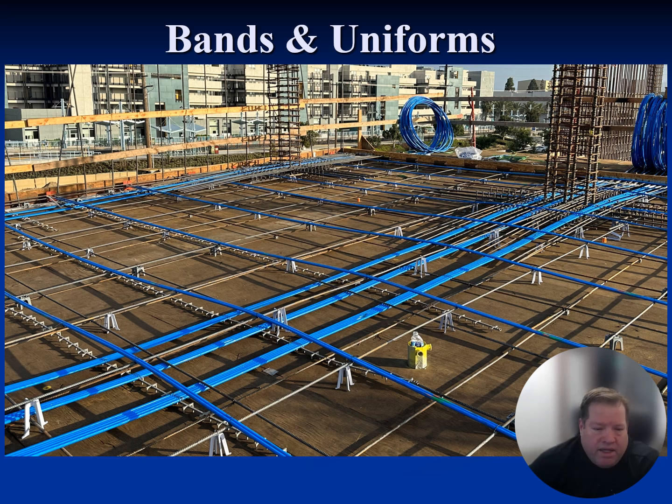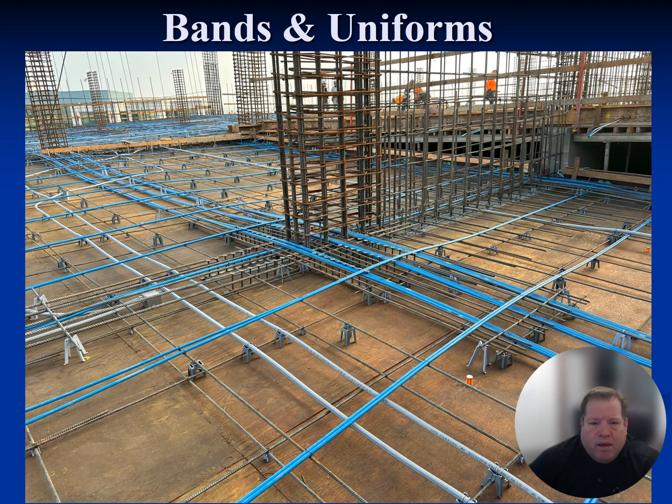But it's a clean system, minimal reinforcement, lots of places to pour concrete, get good consolidation. Like I said before, you can walk the deck, look at all these strands. Very clean, very efficient system for the two-way slab layout.